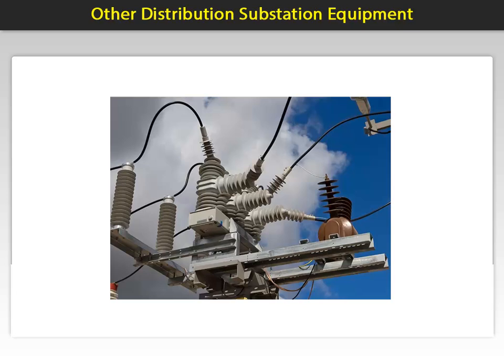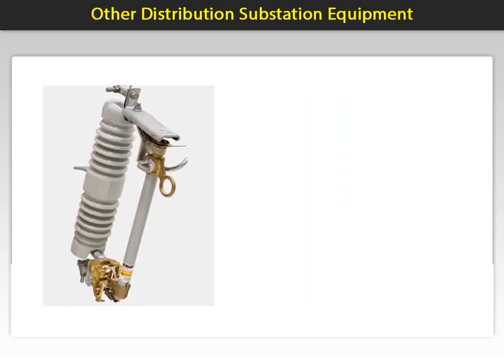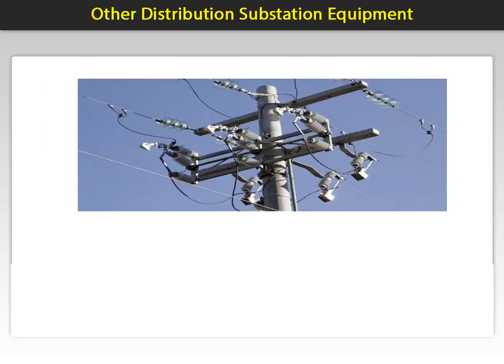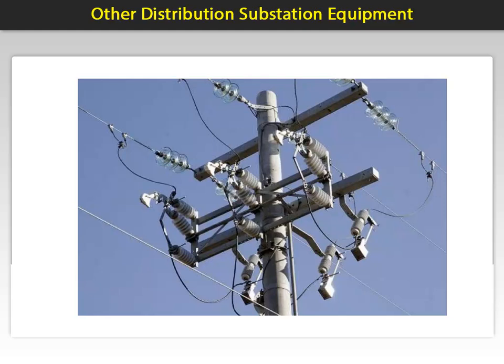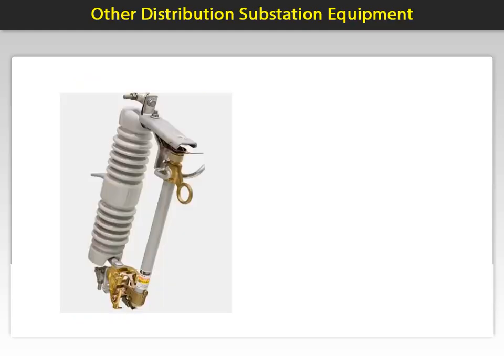In electrical distribution, fuse cutouts are a combination of a fuse and a switch, used primarily in overhead feeder lines and taps to protect distribution transformers from current surges and overloads. An overcurrent caused by a fault in the transformer or customer circuit will cause the fuse to melt, disconnecting the transformer from the line. A cutout consists of three major components. First, the cutout body is an open, C-shaped frame that supports the fuse holder and a ribbed porcelain or polymer insulator that electrically isolates the conductive portions of the assembly from the support to which the insulator is fastened.